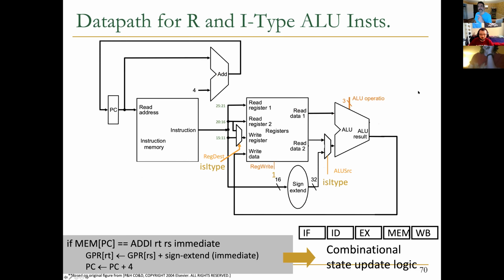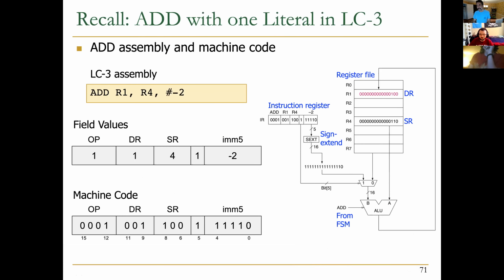Clear all drawing. Okay. This is also a very similar microarchitecture for LC3. LC3 has an add, and if you remember, you could have it with 2 registers, or having an immediate, depending on how you want it, depending on this 1 bit. If this was 1, you should sign extend this and use it as the second operand. Otherwise you had this second register where you could add the values of these 2 registers and write the data back to the destination register, right?